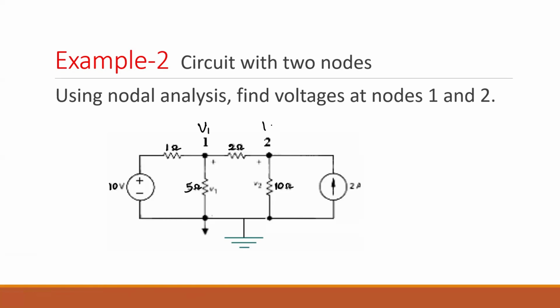So you can say V1 to this and V2 to this. Let's assign currents together so we all have the same names for the currents. So this branch, let's take this as I1, okay? And I assume this current is going down, I2. And from here to here, we may have a current of I3. This one may be a current of I4. This is already known, 2 amps, so we don't need to put an I value. We can say 2 amps to this. So are you okay with assigning currents? Anyone have any issues with assigning currents? So we just assigned currents.